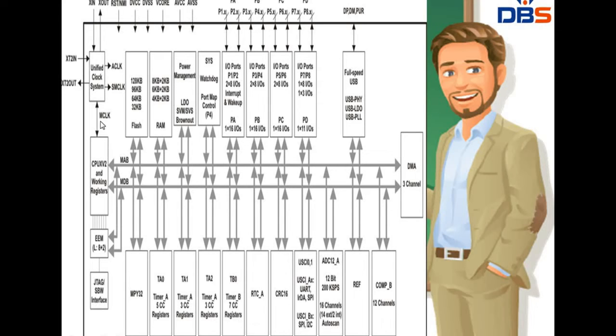This is useful: if I am using MCLK, at that time I am not using the other 2 clock pulses. If I am using ACLK, at that time I am not using MCLK. If we are using all 3 clocks, it is going to consume more power. So in order to reduce power, once it is using MCLK, the others will not be in use.